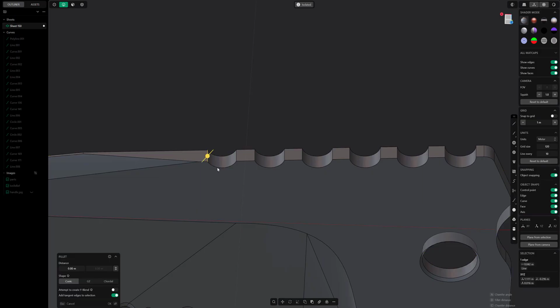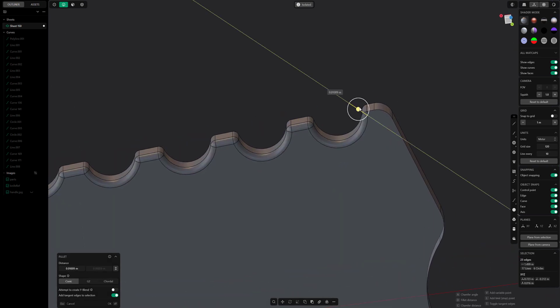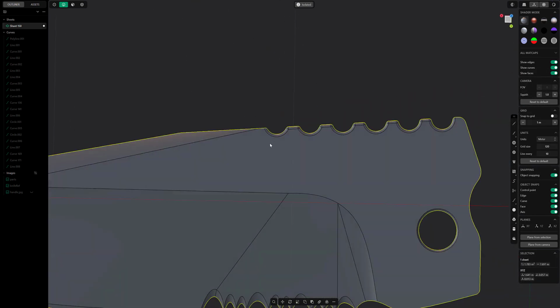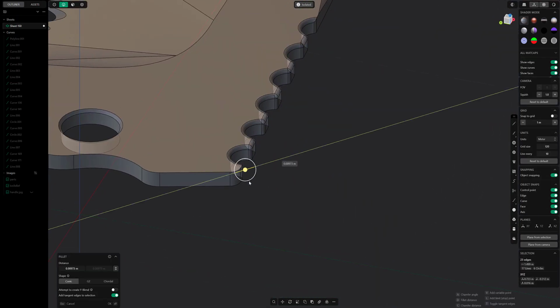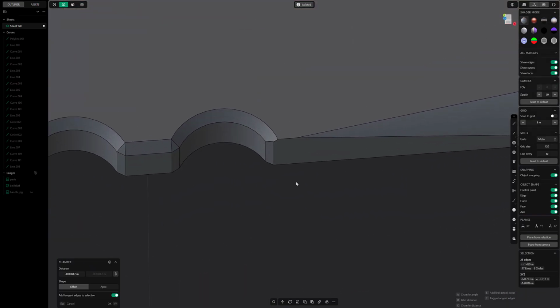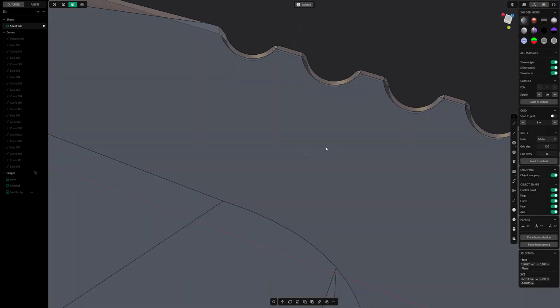At the top, I want to give, again, a machine finish. So I go ahead and just select all of these and I chamfer them. That looks soft, right? So that's not the look I'm going for. So I want to chamfer them just a little bit. Gives a really nice kind of cool finish. And then here I can just push face for this transition to match up a little bit nicer.